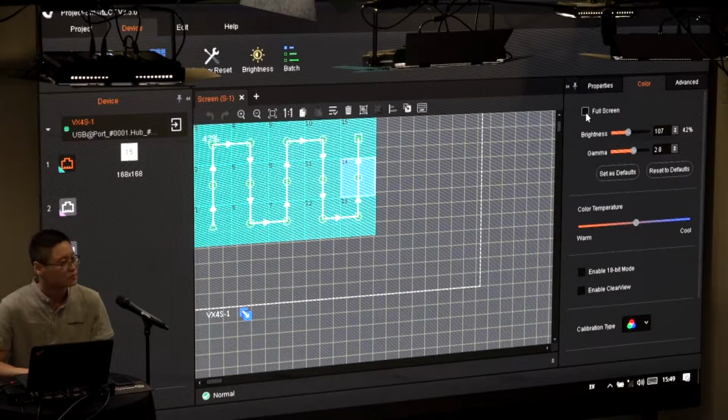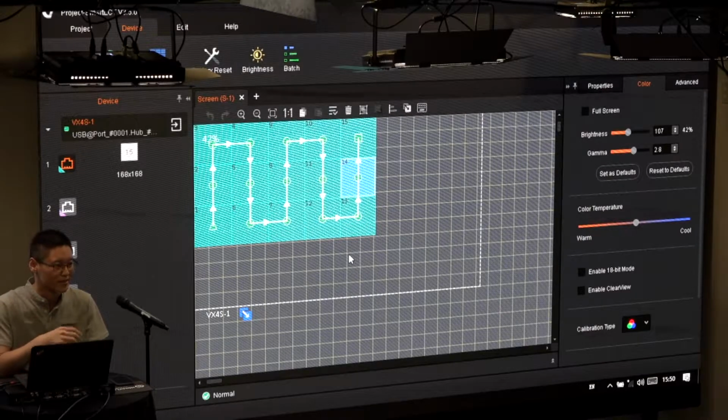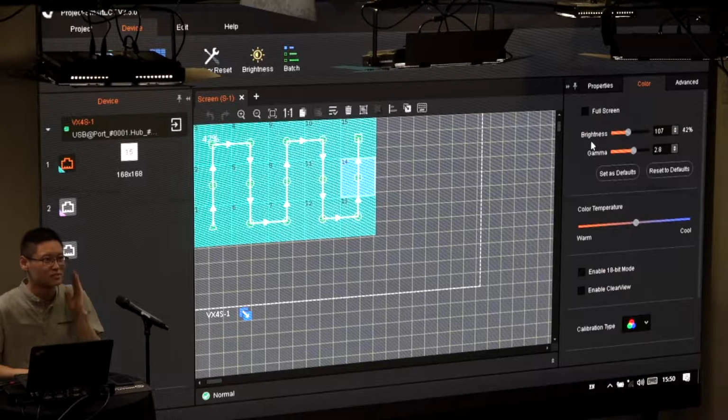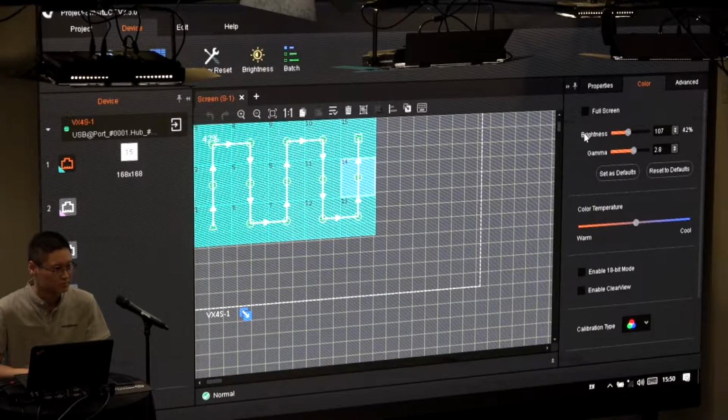Would that be the example of replacing a newer module on a display that's a couple years old, to get that one new module to match the others? Yeah, you can do it, or you can do the calibration I just mentioned, manually adjusting the coefficients. But we recommend manually adjusting the coefficients, because here it's just temporary, but the calibration coefficients are permanent.